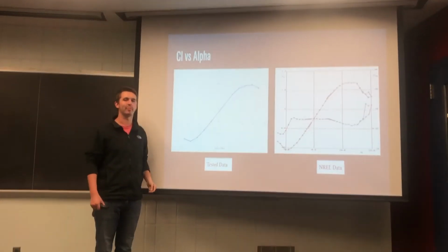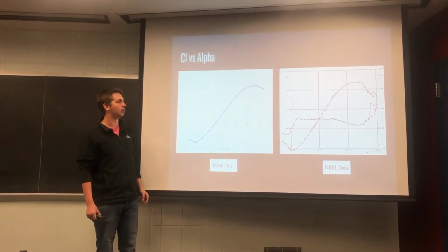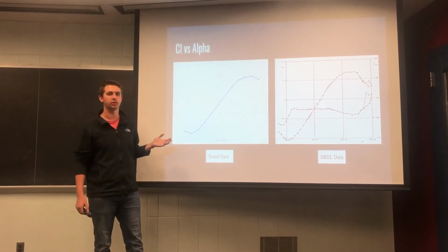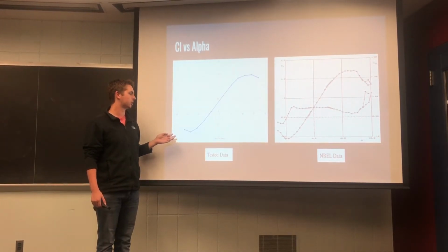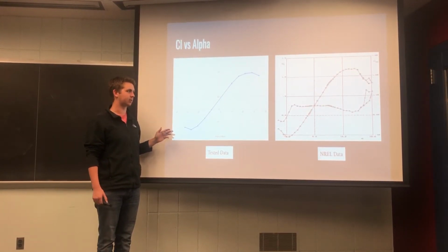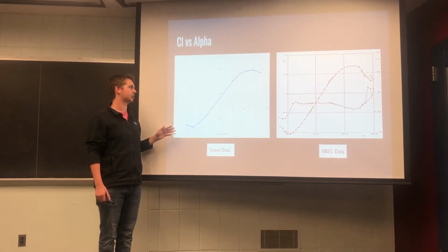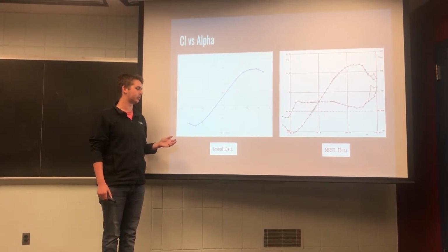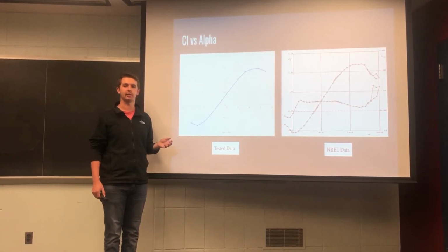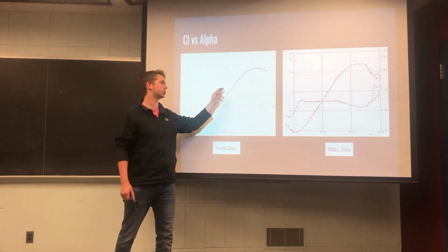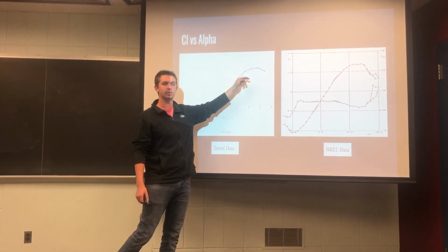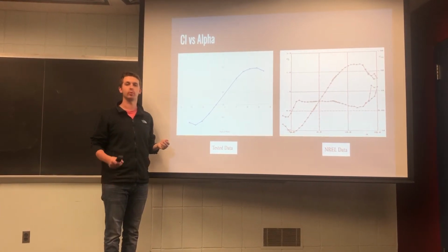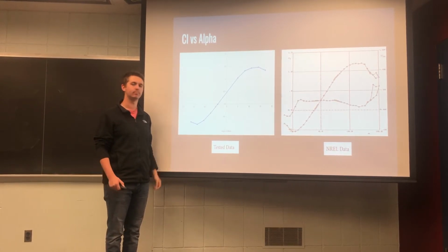Now this is slightly off some of the magnitudes that was calculated from the NREL, where some of those values are around 1.25 for a max and -0.6 for a minimum. So those values are slightly off, but we follow the same trend. And additionally, we can look at this CL versus alpha graph and match it up to our stall locations at the different angles of attack as our CL starts to decrease at roughly around 17 degrees and -16 degrees, which is where we experienced stall when we were listening for separated flow.